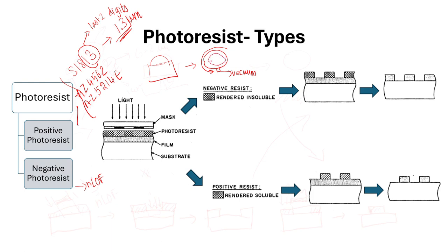Depending on the duration and the RPM, we start to spin. The centrifugal force will cause the dispensed photoresist to spread across the substrate. Once the coating process is done, the photoresist will have deposited across the entire wafer surface. So that is what happens.